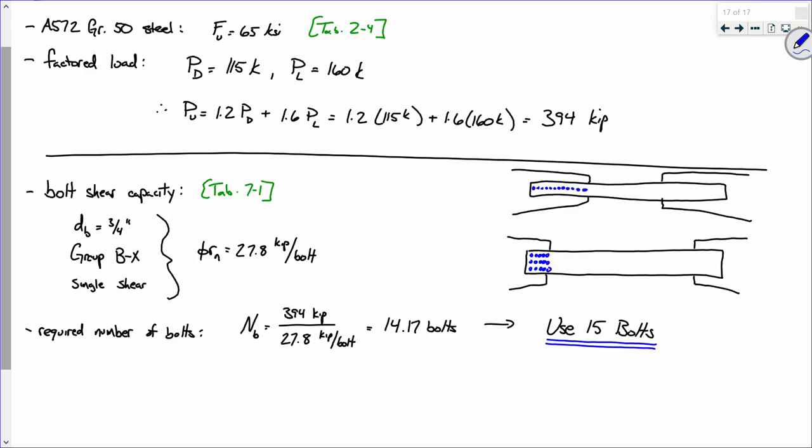Go to the awning that's between the old engineering building and the new engineering building and look up. Look at those floor beams that are framing in, and look at some of those connections that only have like 2 bolts, okay? There are plenty of instances where the shear force on one of those beams due to that snow is not a lot, okay? It's really not a lot of force. And you really probably don't need any more than 1 bolt. You place 2 in there for OSHA requirements and for redundancy.